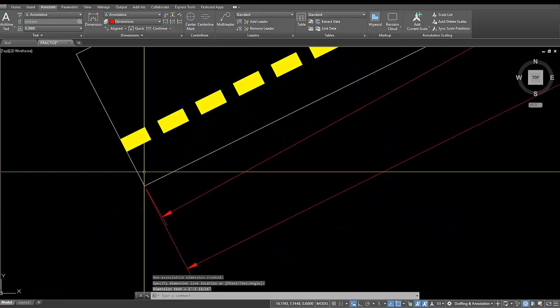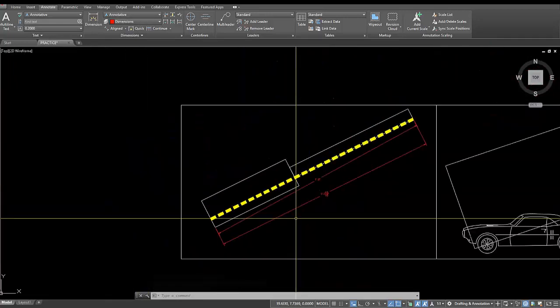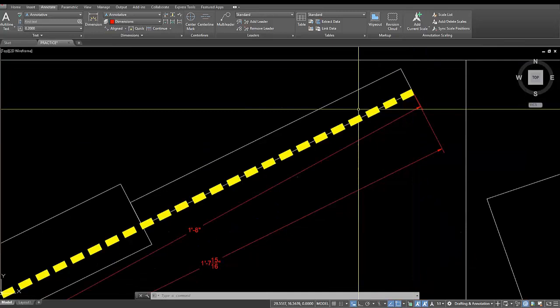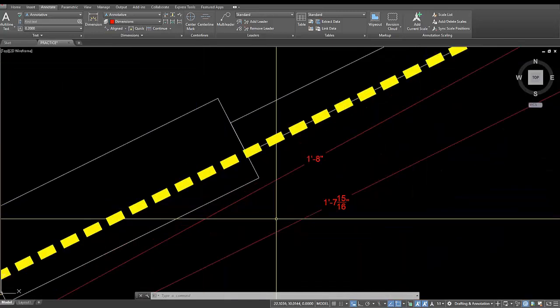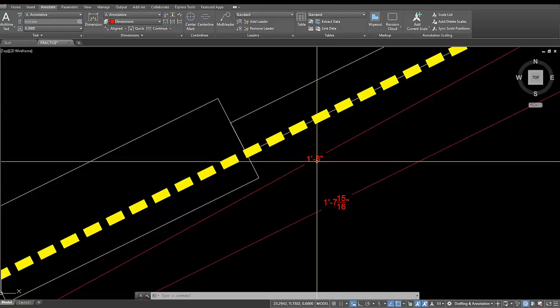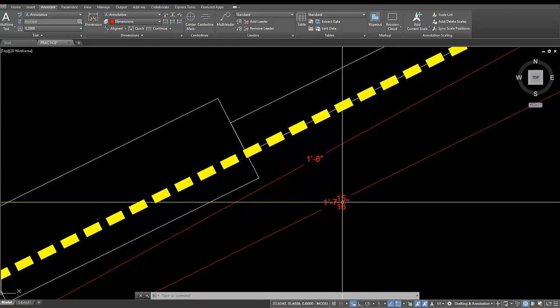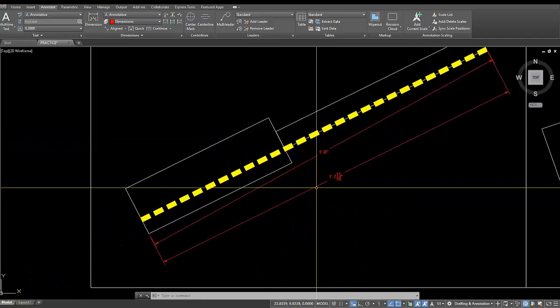And you'll notice that the dimension line comes right off this corner instead of at the yellow line, as well as the alternate corner up here. Clearly, there are two different dimensions between the aligned and dim rotated option, so you want to make sure that you're using the most applicable dimension possible to get the right information.